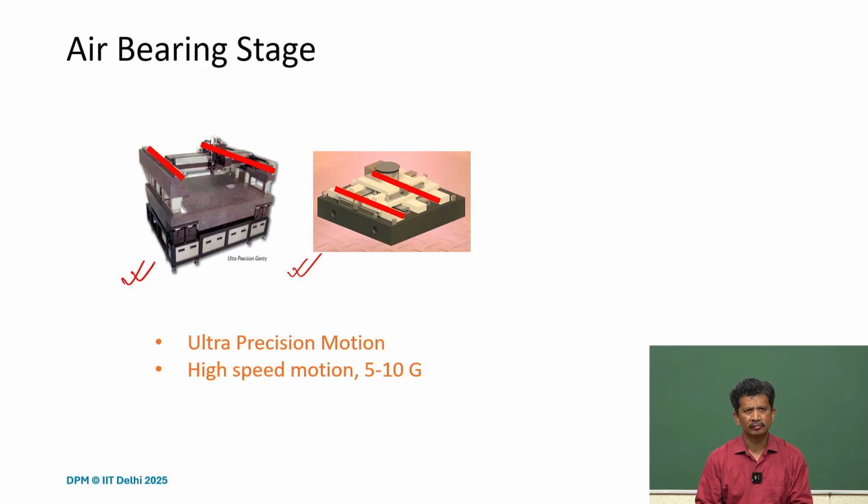What you notice is that these linear guideways are running on air bearings, and it can be orifice type or it can be porous type. So those are the configurations and those are the elements. We'll try to understand the requirements and how to achieve those specifications right from the beginning, how to ensure that we can achieve that.